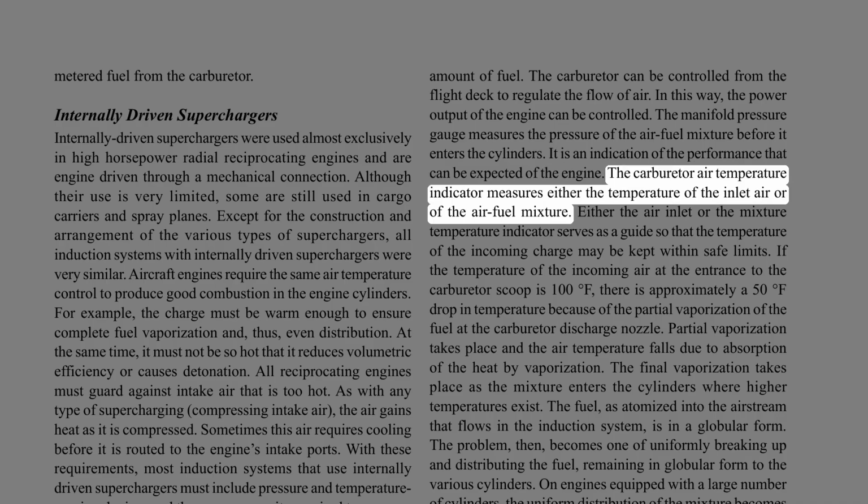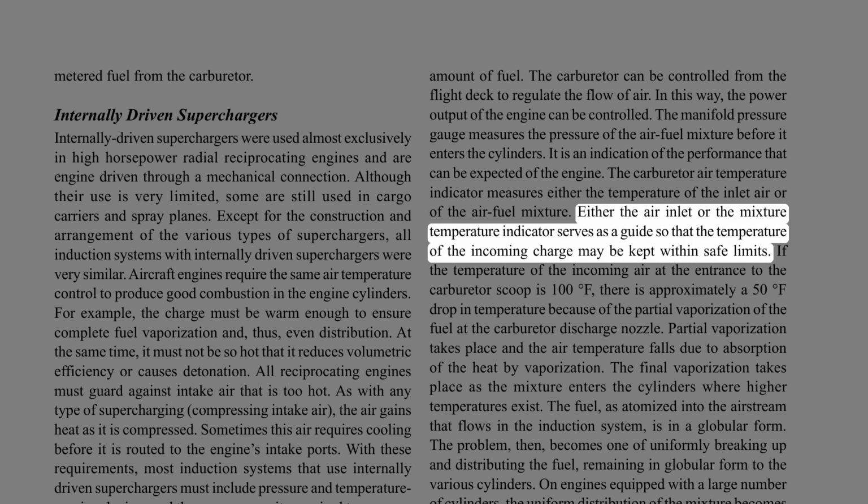The carburetor air temperature indicator measures either the temperature of the inlet air or of the air-fuel mixture. Either the air inlet or the mixture temperature indicator serves as a guide so that the temperature of the incoming charge may be kept within safe limits.